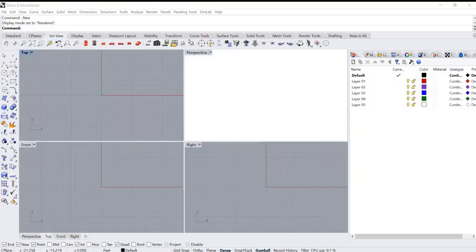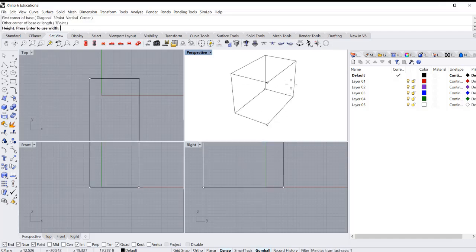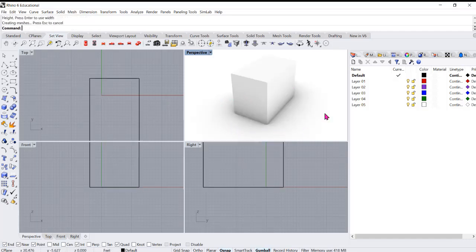Now, before we start placing artificial lights, I want you to be aware that whenever you open and create a new file using any of the templates, by default Rhino will use the environment lighting or the skylight on each scene. That's why when you place any geometry and you go to the default render mode, you see a kind of shading or environmental shade on the object. This is using some of your computer memory.